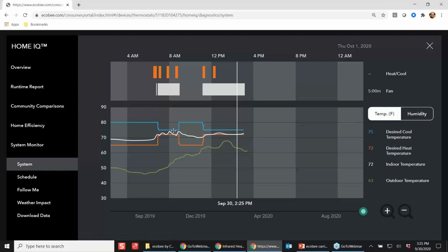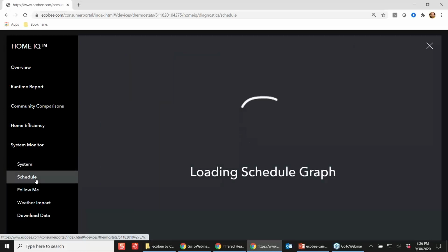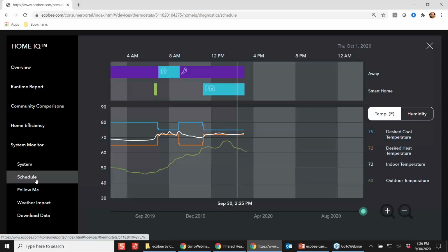But the other thing that's cool is you can see how much heating and cooling run hours you get. So what I would want you to do is look at some of these stats on really cold or really hot days and just see how little they actually run. If it's a 0 degree day outside, it should be a solid orange bar that never turns off. It should never be able to fully keep up, right? But if you see it like this and it's not solid orange, that means it's cycling on and off, which means it's oversized. So later on when I go to give them a new system, I feel really good about my new load calc and giving them a smaller size unit. And yes, we squeezed in oversizing once more.